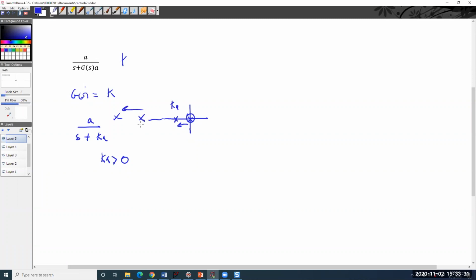And so if they said bring it in control, and I want a pole at 100, right? Let's say A equal to 1,000. And you say, I want my new pole to be on the left-hand side, and I want it to be minus 100, right? Well, then I would set K A equal to, well, actually, I would just do that, because I know it's going to go on the proper side. So in this case, K would be 1/10, right? And would put the pole exactly where I wanted it.